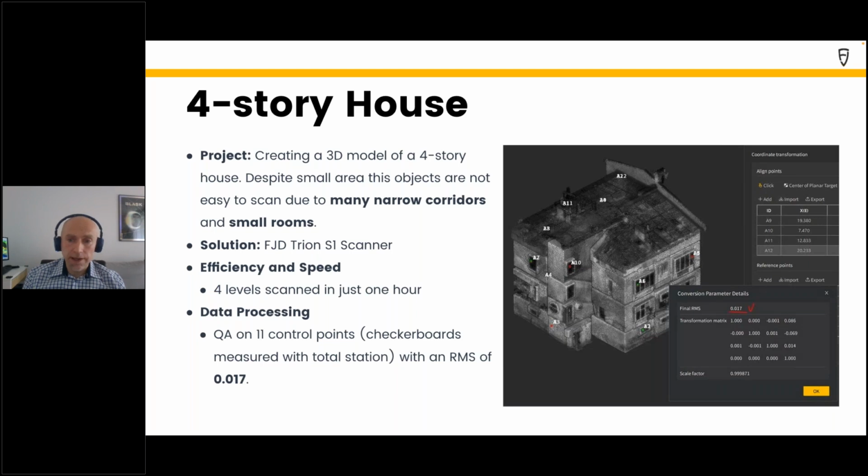As you probably guess, I did it by means of a control network. I'm a surveyor, and these were checkerboards placed on the perimeter of each floor. This is very important: place them on the perimeter in every axis. In this way, you can control every coordinate, you control the levelness of your scan.